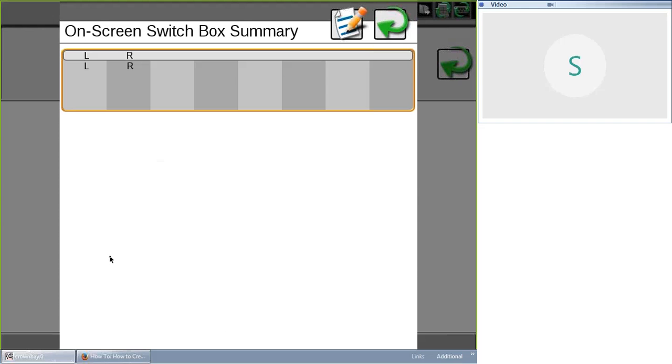What the on-screen switch box does, this is our switch box for AccuBoom, where we can override our sections on, off, or into Accu position. This is real handy if you have a spinner machine. You can set up that spinner section as its own section, and if we're controlling spinner speed, you can override that on so AccuBoom's not controlling that spinner. I'll show you a little bit more about the on-screen switch box once we get within a job.